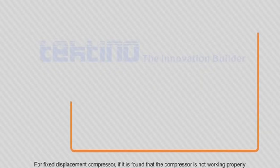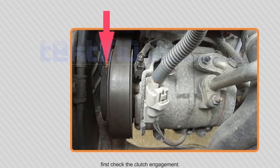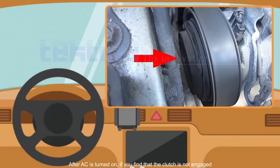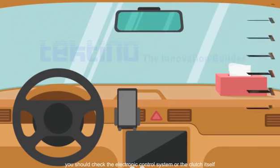For fixed displacement compressor, if it is found that the compressor is not working properly, first check the clutch engagement. After AC is turned on, if you find that the clutch is not engaged, you should check the electronic control system or the clutch itself.